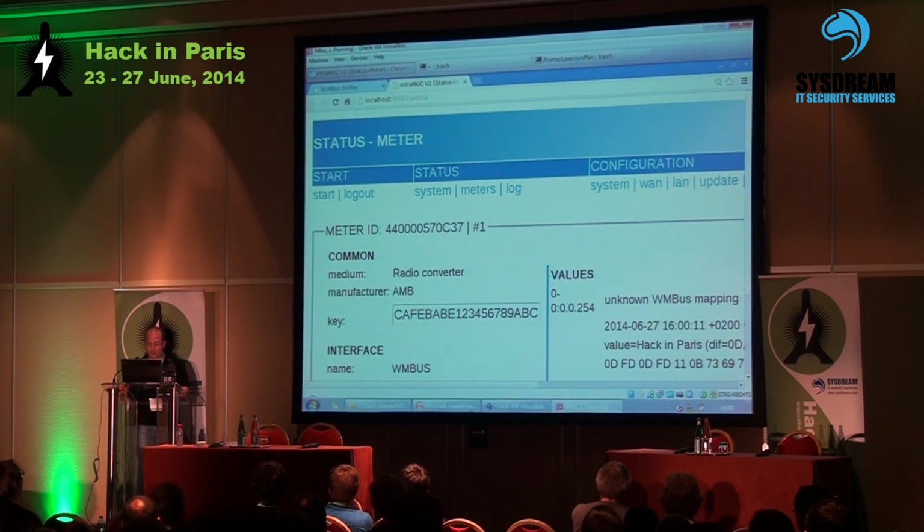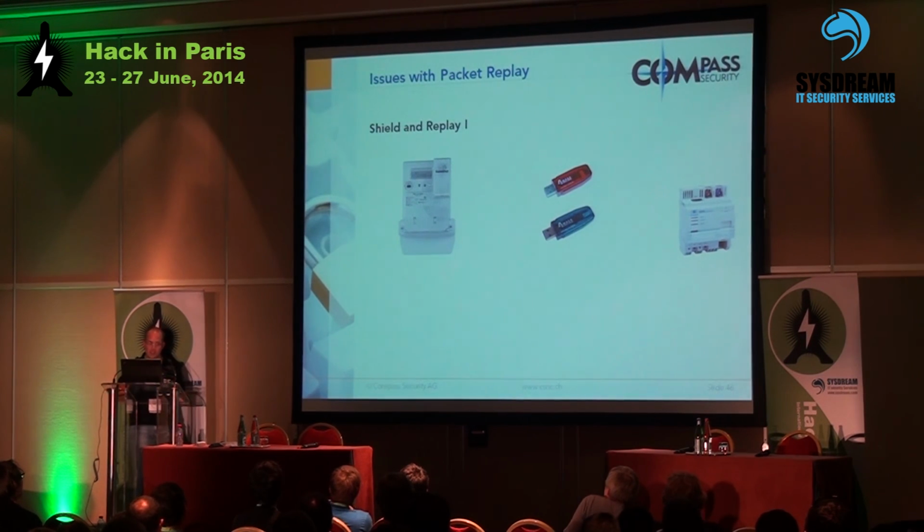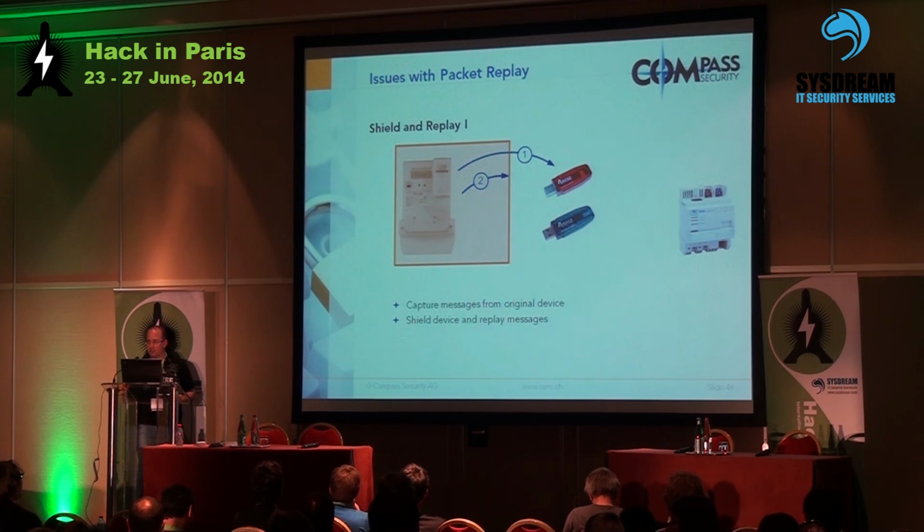But you maybe recognized I just stopped the meter, because in the real world it's slightly more difficult. Because when I just send another value, the meter will still send its original value a few seconds after. So what you need to do is basically capture a packet, then either shield the meter or take a big hammer and break it, and then repeat it.